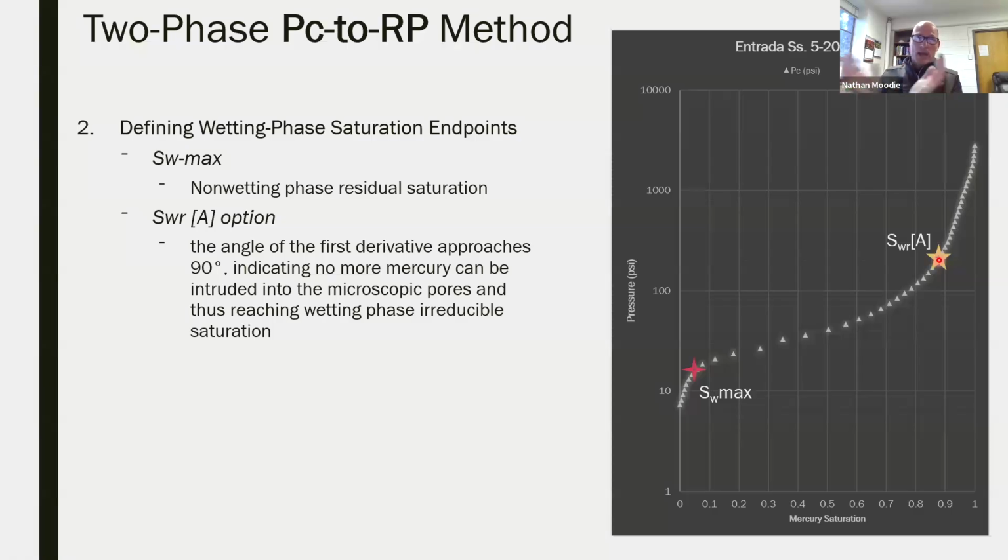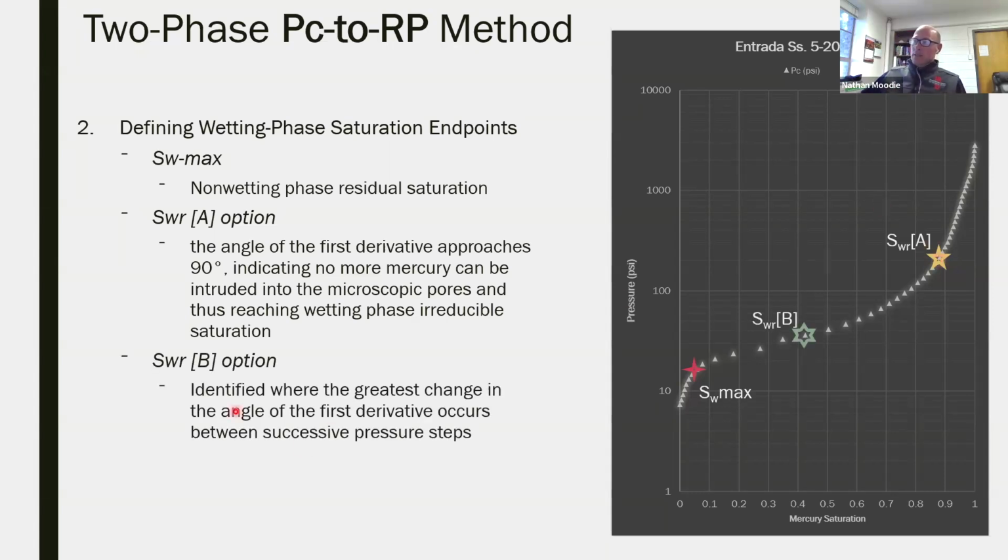And sometimes that doesn't match what the laboratory data would be showing you, or if you think you want to pick that critical saturation point. So this was the greatest challenge for me to try and figure out, how do we do this? How do we pick this point? And this, depending on the curve, is the most uncertain point that we pick. Just as a caveat, this is one where sometimes the algorithm won't pick the right point,